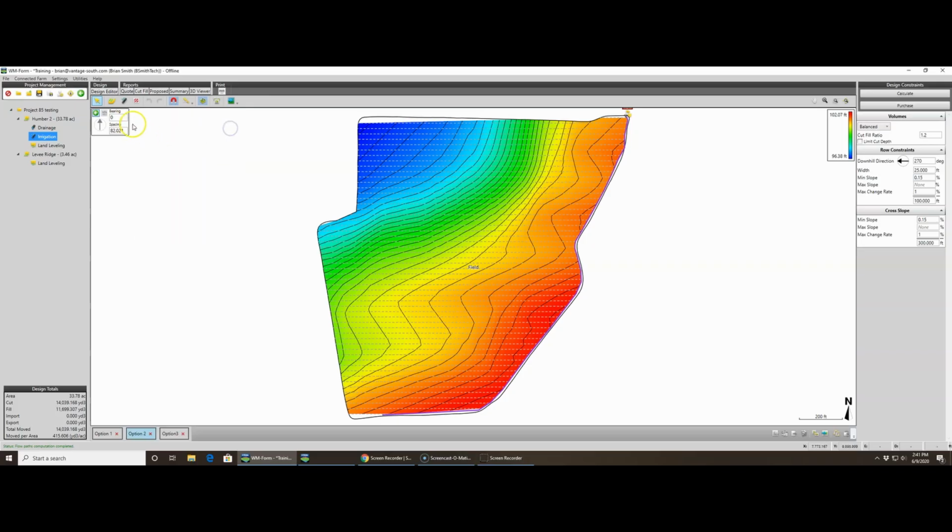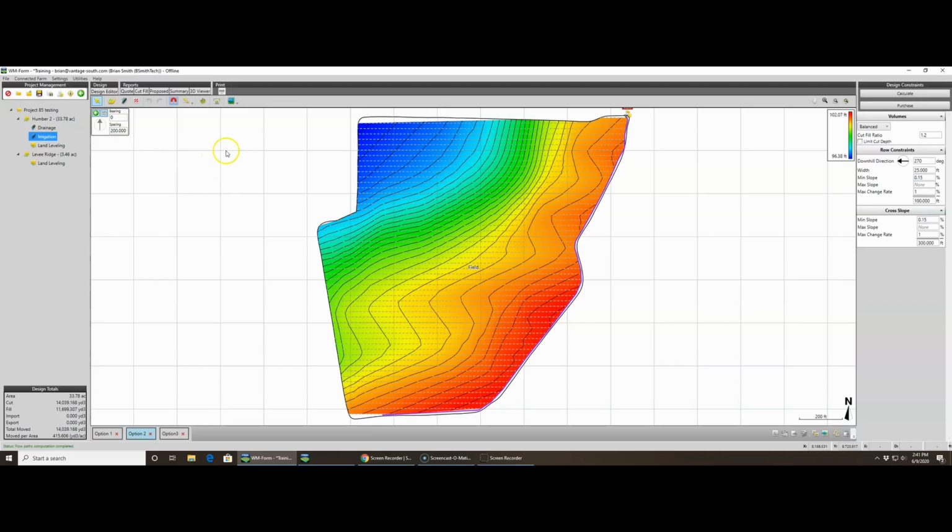Let's talk a little bit about this little icon right here in the top left of the design page, your bearing and spacing. So spacing comes up with 82.8 and 82.02, and I like to just put something in there that I can understand, so I just put in 200, and then you turn this on by show visible grid. So your bearing is 0. This is 0 and 180 and 270 and 90, and each one of these lines now is 200 foot apart.